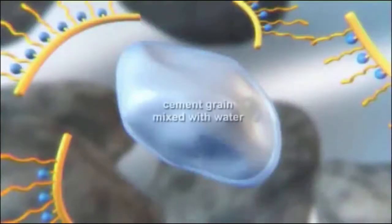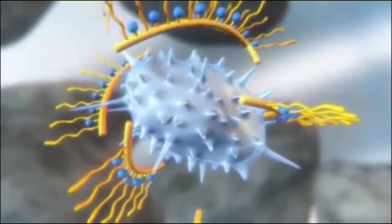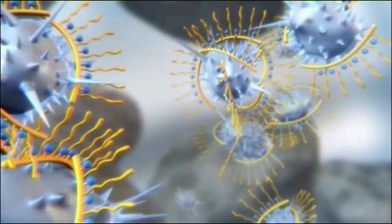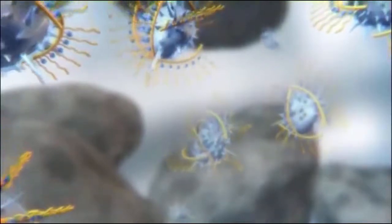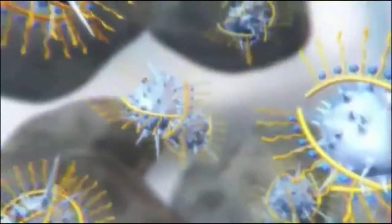When cement is mixed with water, it reacts and starts to form crystalline needles that interlock with each other to form a hard, rock-like substance. When the PCE molecules are mixed with liquid concrete, they are absorbed onto the surfaces of the particles contained in the concrete. The side chains of the molecules point outwards, like the spines of a chestnut burr, and hold the particles at a distance to each other. This makes it easier for them to move against each other, and the concrete becomes more fluid. Concrete can be given the desired properties by varying the length of the main and side chains.